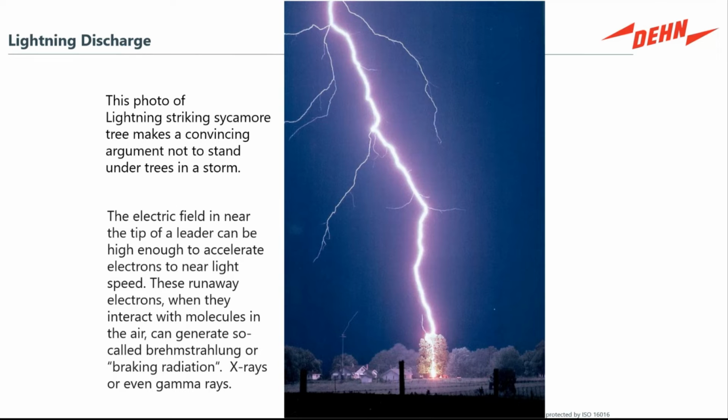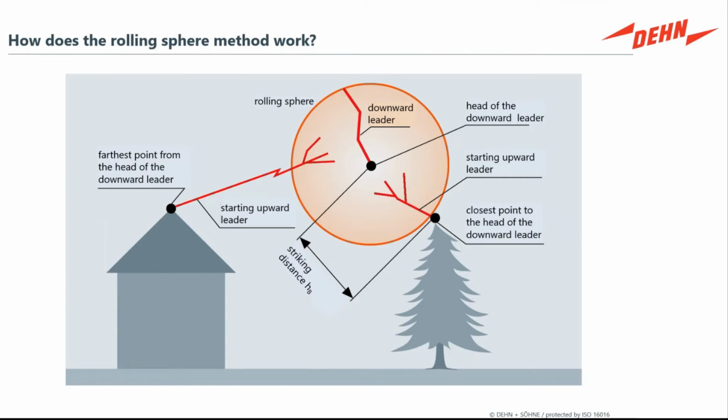But what you see here is a good indication of that visual electric field which provokes the step leader attachment. And so you think of it like a ball of charge that's provoking a huge electric field that's spherical in nature around it. And in that moment that it's attaching, the step leader that is closest wins. All other things being equal, like dielectric breakdown of the atmosphere. But Ben Franklin discovered that premise that if you put a lightning rod up higher than the structure, it is likely to strike the rod due to that electric field attachment.